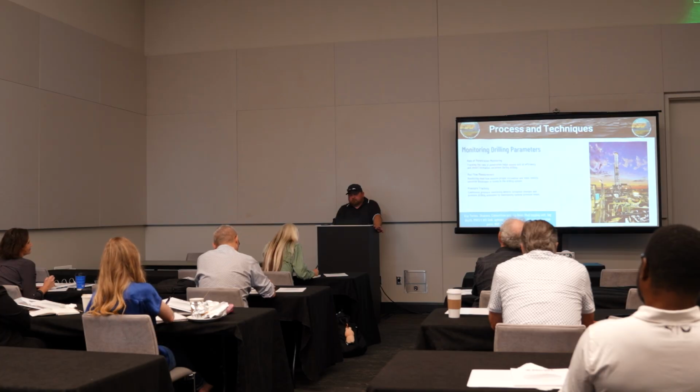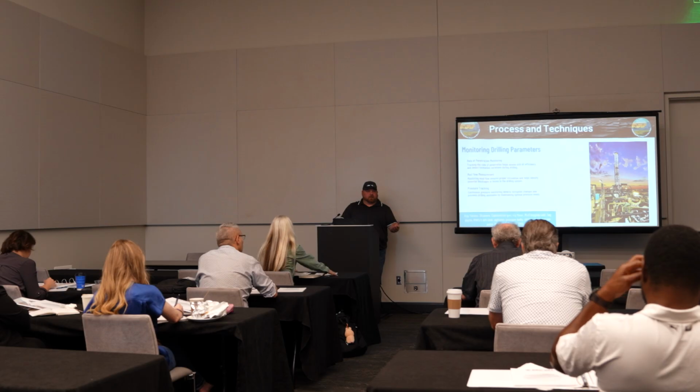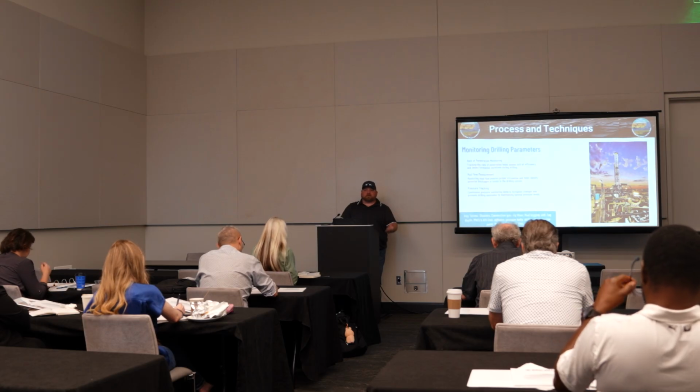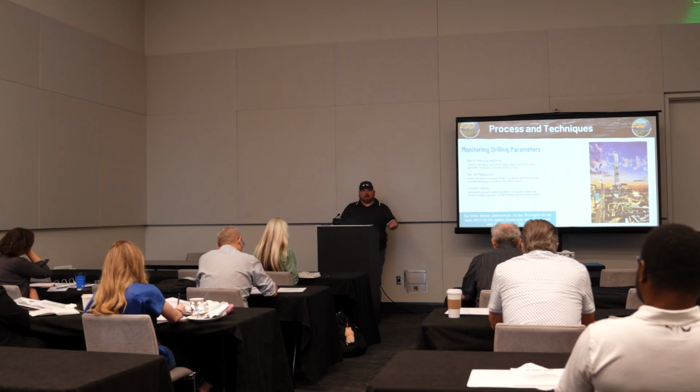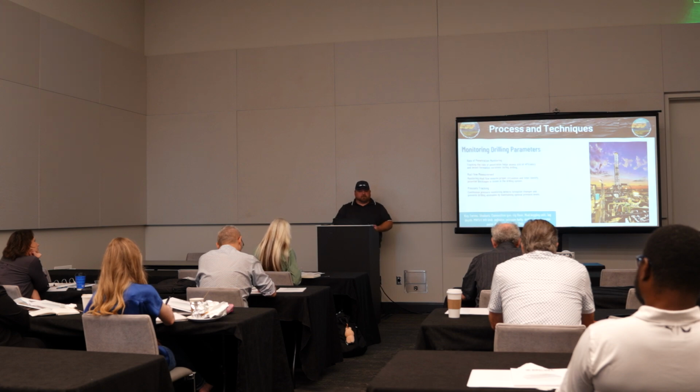Mud flow. Keeping an eye on your mud flow helps to ensure you're getting your gas agitator in the mud consistently while you're drilling. If you see a dip in the flow percentage, that's going to bring the mud level down from where your agitator is sitting, so it's going to affect your reading as well. If you take a kick of gas into the wellbore, it's going to bring volume up with it. So it's going to bring that percentage of mud flow up and drown your agitator.